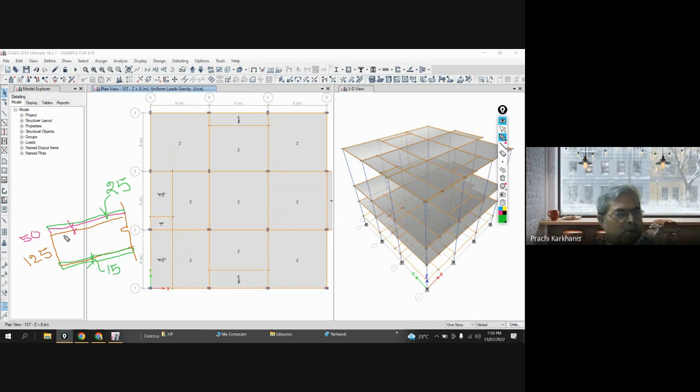Okay, so this part is built in, so I don't have to worry about this part, which is the thickness of slab, and this is applied from the bottom, say ceiling. So what is the total thickness? 50 plus 25, 75, plus 15. How much is it? 90. Let's say 90 mm. Right now I am considering the density of all as 20.